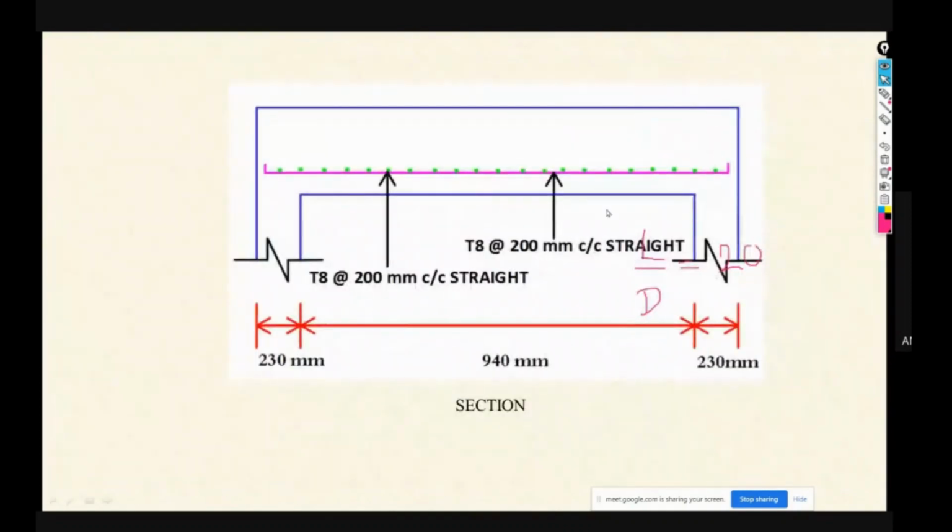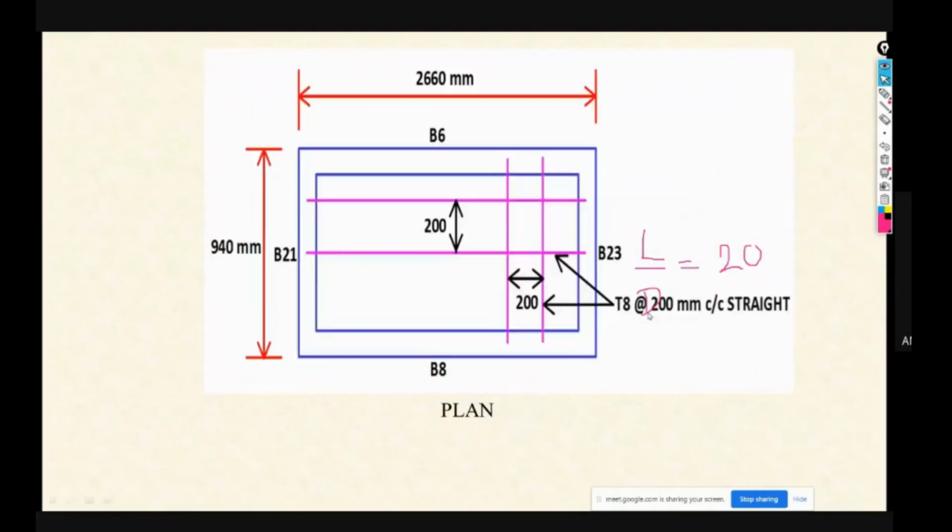And then directly just provide the reinforcement. We know the minimum main steel we are providing along the shorter span, and distribution steel along the longer span. Generally here in the calculations, the reinforcement in the shorter span and longer span is the same. So this is the general arrangement. But basically, if you see the main steel, we are providing alternate bent up bars.